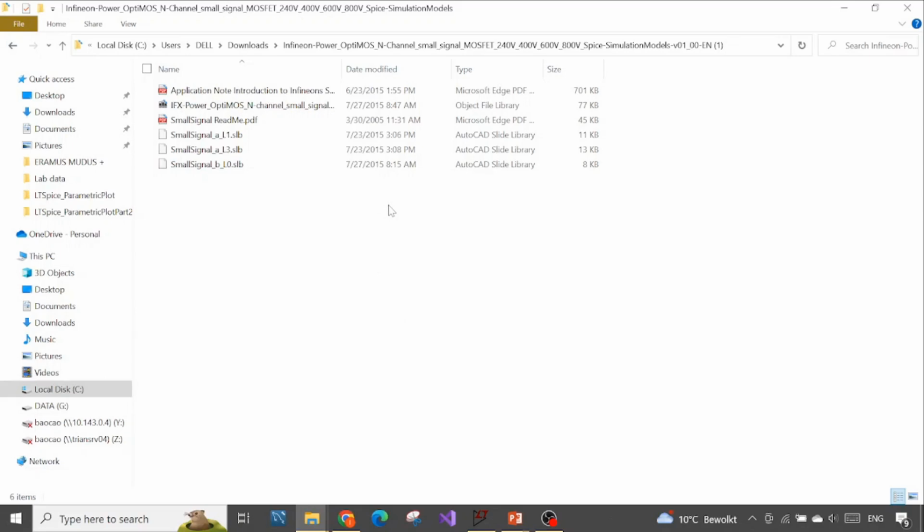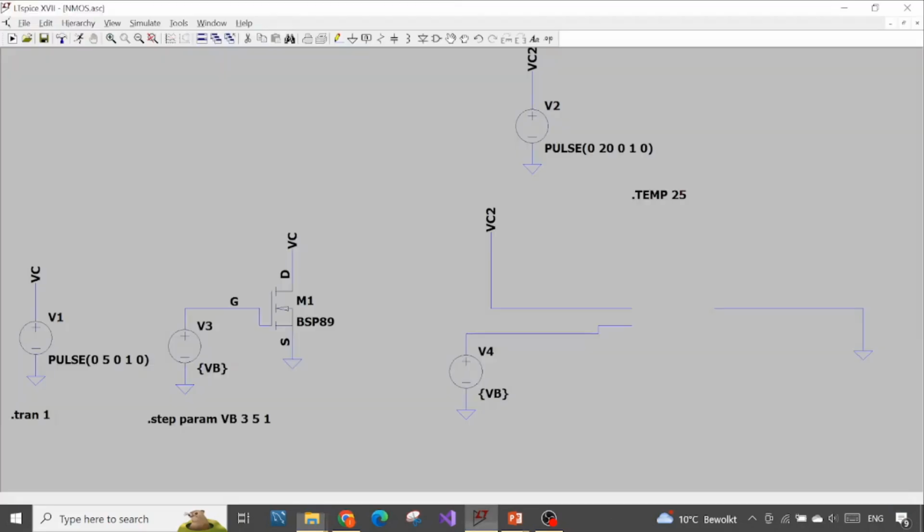In this case, we also import a third-party device from the website, but we will do another step, which is to automatically generate a component rather than drawing it by hand in LTSpice. That's the difference. We will use automatic component generation in LTSpice to have the symbol rather than use a default symbol, because sometimes you don't have a symbol.